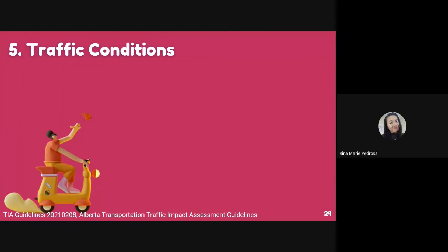of the proposed development. The report should contain information on existing 24-hour traffic volumes and should also provide the existing peak hour turning movement volumes for the major intersections in the study area. The peak hour shall be determined as any time frame that will have the greatest impact to the highway system and that will generate the highest volume of traffic to or from the development on a typical day. Time frame may vary depending on the type of development, but typically should be morning peak from